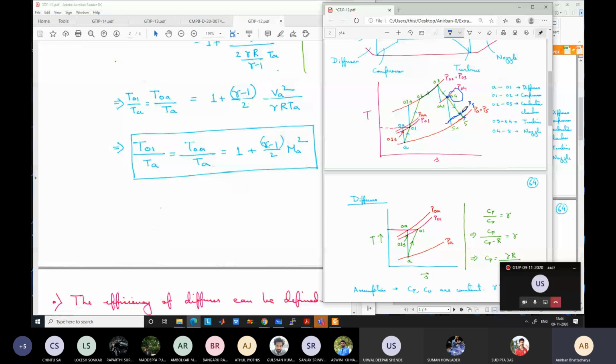But there is another important reason. Say you have found that it is choked, or I have told you that it is a choked nozzle. Still you need to find the pressure for performance calculation. How will you calculate the thrust in this case? What is the equation of thrust? You don't have to tell the exact equation, but physically, tell me what constitutes the thrust. How can we calculate the thrust?